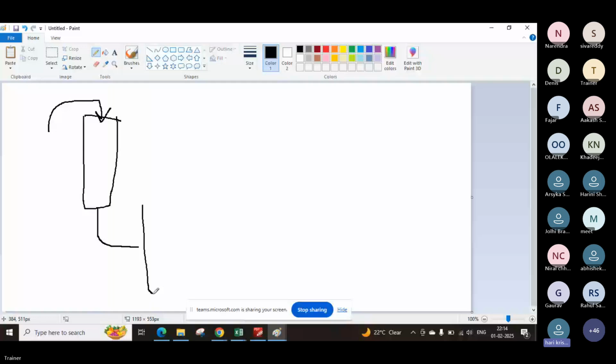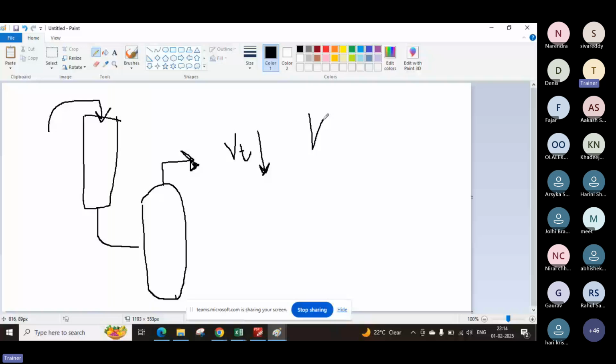Correct. So in this case, what should be the orientation, the liquid level, the gas velocity? No, gas velocity, we do not consider gas velocities ever. I never talked about gas velocities. It's all about the terminal velocities, the liquid dropping velocities, or the K values. If you are using the Souders-Brown equation, you have to use the K value. If you are using the GPSA equations, you have to consider VT values.